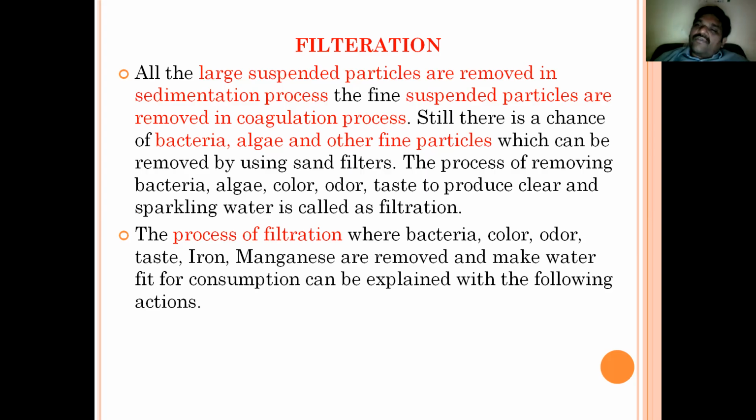Of course, we removed the heavy particles as well as fine colloidal particles, but it doesn't mean that the water is in pure condition. Still, there are certain impurities like bacteria, algae, and other fine particles. They also must be removed from the water before we supply the water to the public.